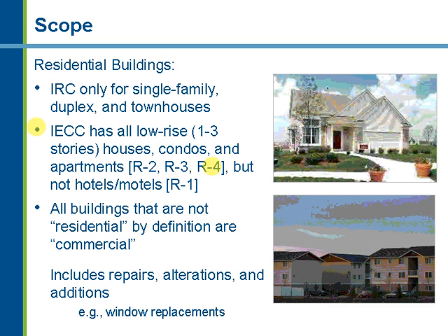So, buildings that are not designated as residential, how are they defined in the IECC? They would move over under the definition of a commercial building, whether it's a high-rise apartment complex or so forth, and that's where the limitation comes in. If it is greater than 3 stories, it falls under the commercial code. There are also some requirements for repairs, alterations, and additions.